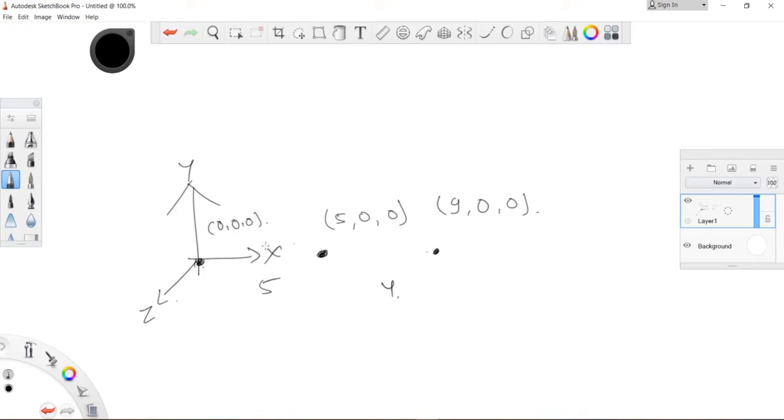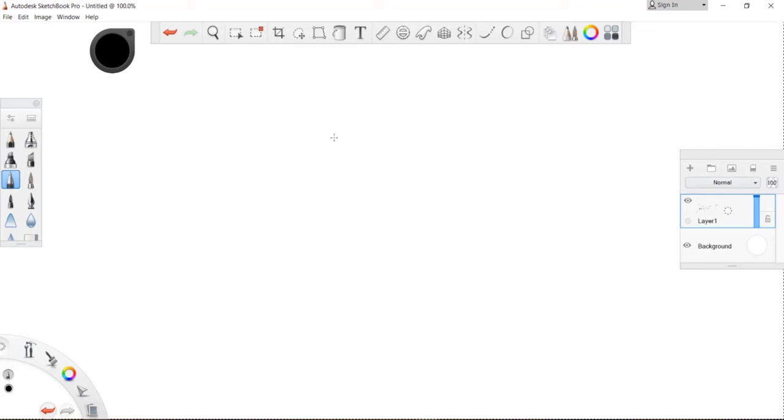But once you get these 3 points, 1, 2, 3, you can simply join these points to draw the beam. And after drawing the beam, you can give the supports, and after that you can apply the loads, and you can analyze and design your structure. Let us consider a simple beam and apply simple loads on that beam. So let me delete these things. I'll draw a simple beam over here. For the beam over here, let us give a fixed support on this end.